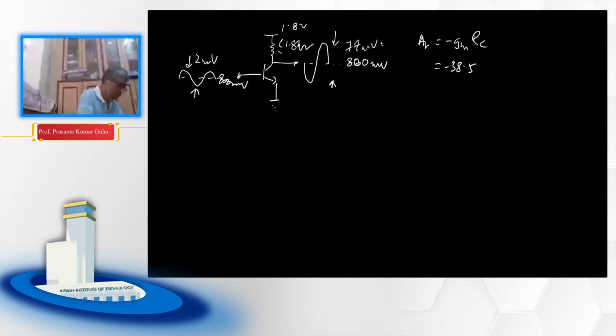and so on. The only thing I would like to point out here is your VCC has an important role to play to find out your maximum gain which you can achieve. Beyond that it will go to the saturation and distortion will occur and all that. Again, you can find in this simple circuit the corresponding input and output resistance that I have discussed already in the last class. Let me reiterate once more.